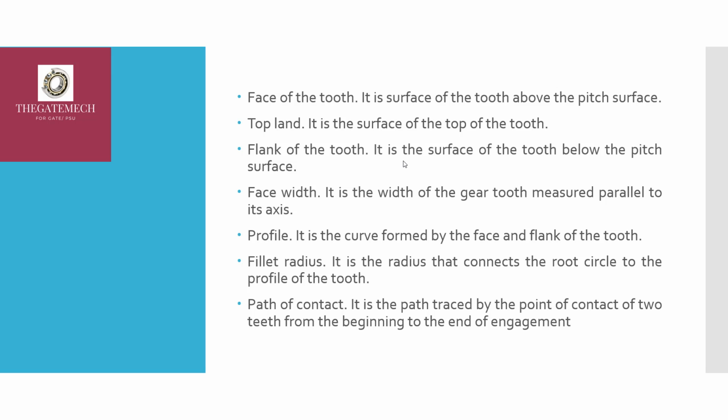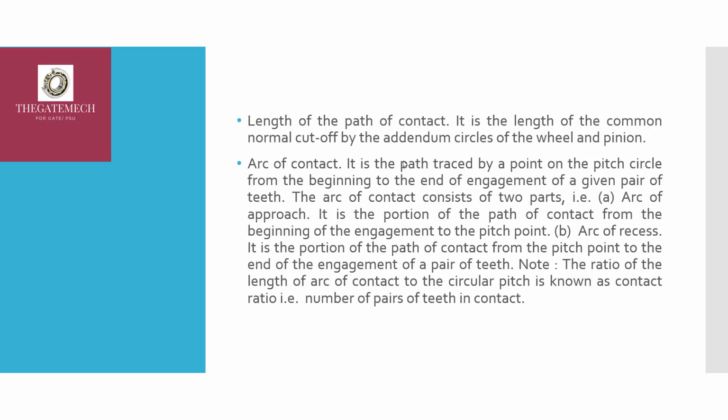Path of contact is the path traced by the point of contact of two teeth from the beginning to the end of engagement. Length of the path of contact is the length of the common normal cut off by the addendum circles of the wheel and pinion.